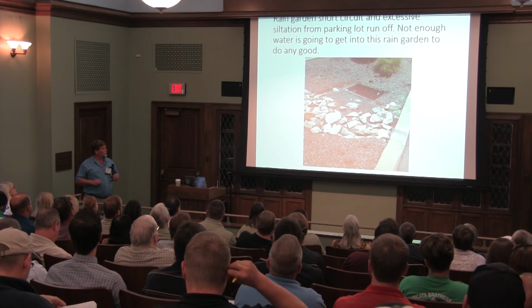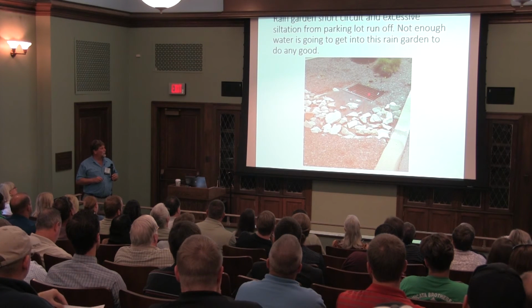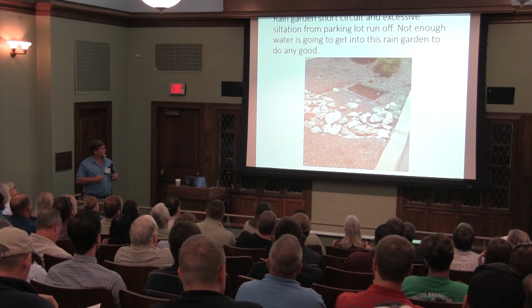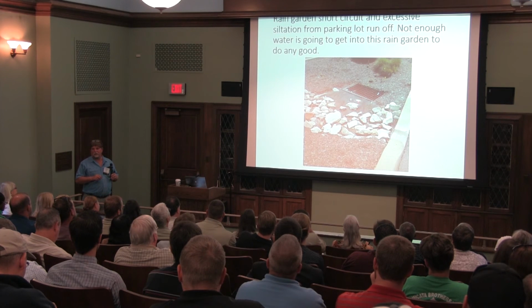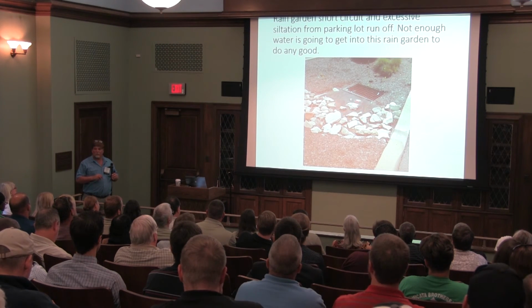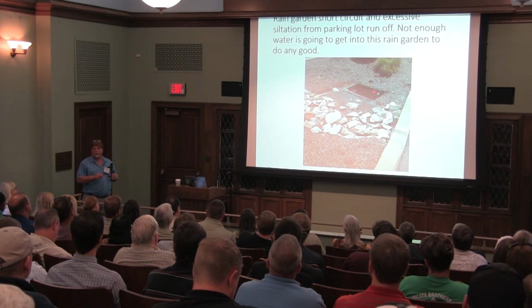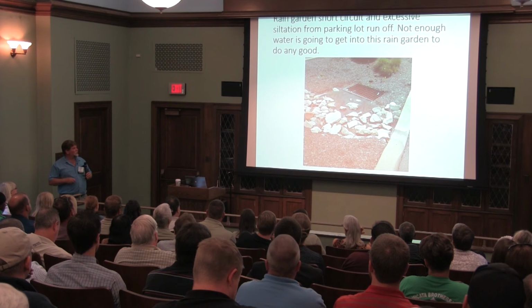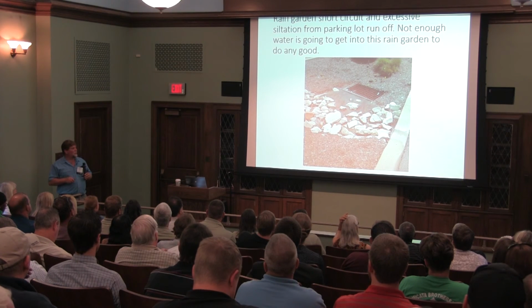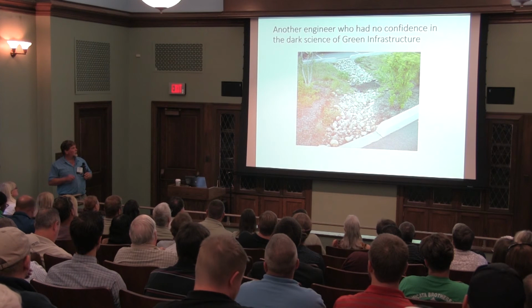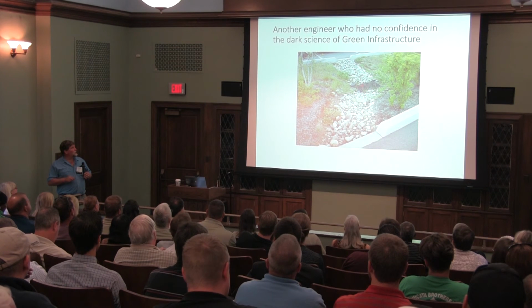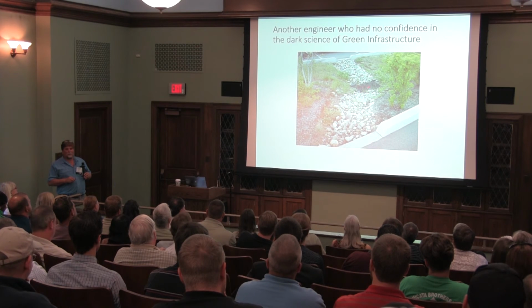This is showing a couple problems. This is siltation that came off the parking lot. That is motor oil, gunk, garbage, rubber tire particles that are heading into that drain. Okay? That's the kind of stuff that comes off the parking lots that goes into the rain gardens, contaminates. Now, the other issue is this opening is across from the inlet.